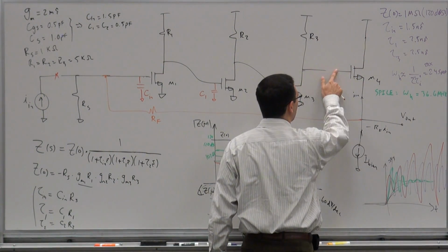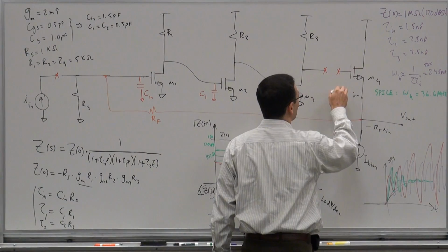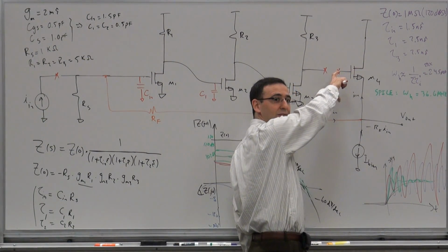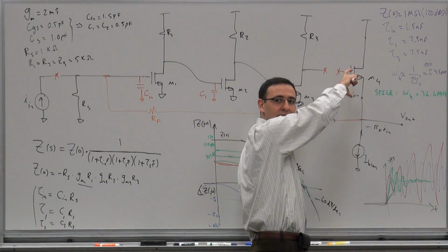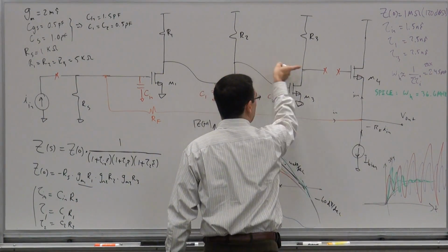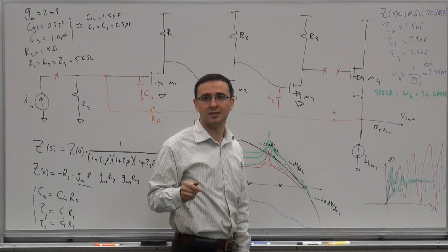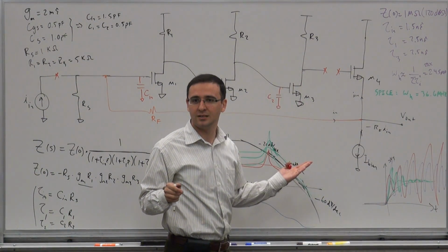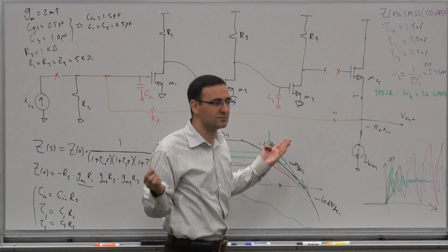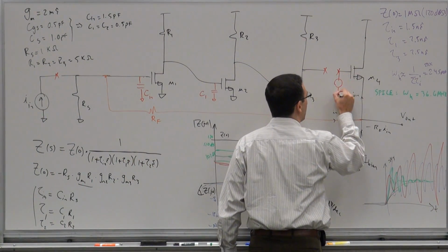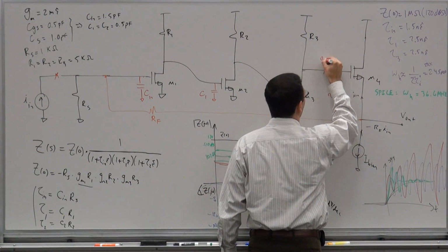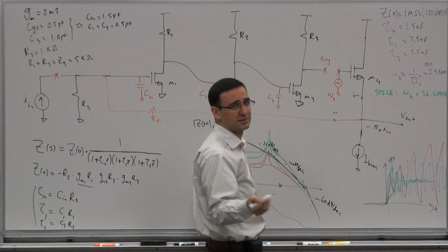This is the place where I have an open. So if I put a current source into here, I get infinite voltage here, right? So whatever comes back to infinity, small signal model. So Ti is infinity, so I need to only worry about Tv. So I can apply a Vx here and Vy. And if I couldn't, I have to do both, which is fine.